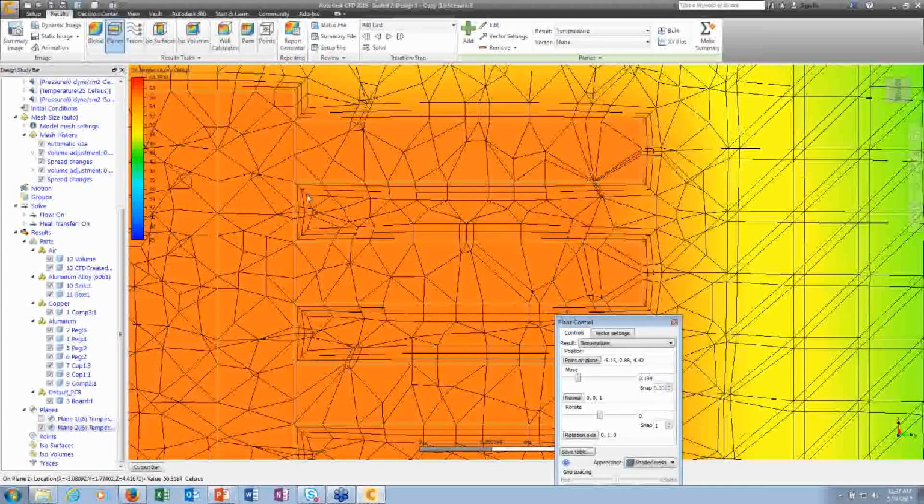So you force the mesh to happen between those volumes. This is something that is commonly used just to force mesh layers to be where you want them to be and not anywhere else in the model. This will save you a lot of mesh if you do it that way. It might be a little bit of work inside your CAD, but it's not too bad. Basically creating those volumes here that will force mesh to happen where you want it to.